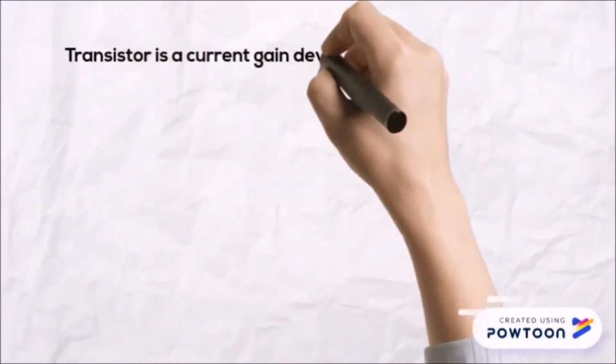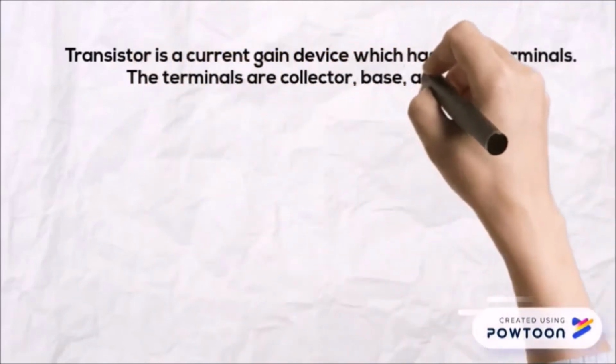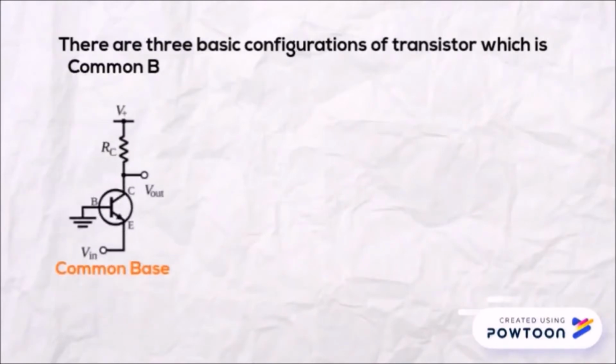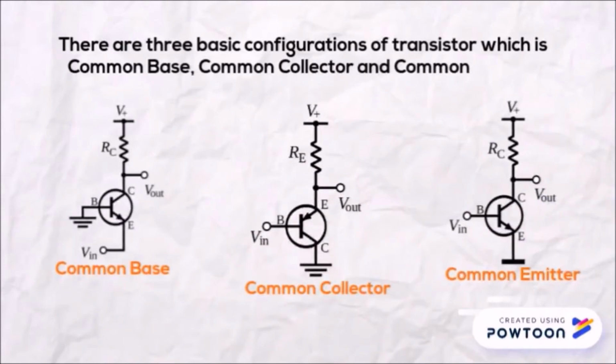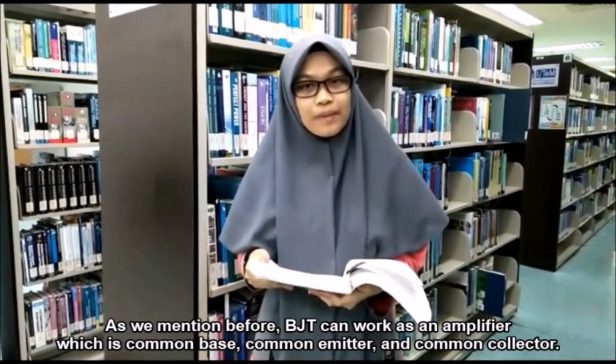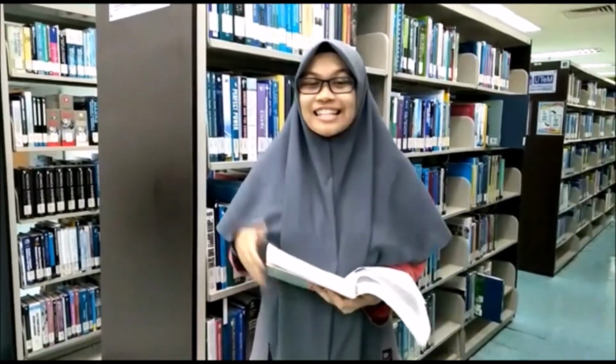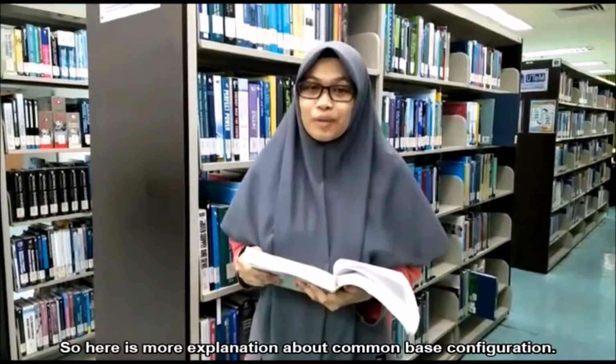A transistor is a current gain device which has three terminals. The terminals are collector, base, and emitter. There are three basic configurations of transistor: common base, common collector, and common emitter. As we mentioned before, BJT can work as an amplifier in common base, common emitter, and common collector configurations. In this video, we will only focus on the common base configuration. So here is more explanation about the common base configuration.